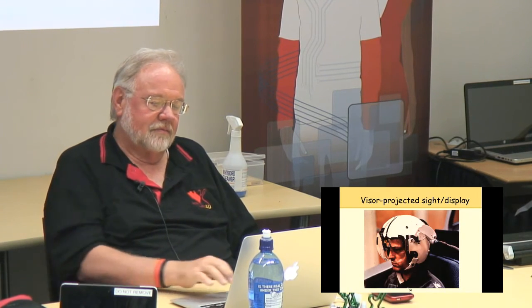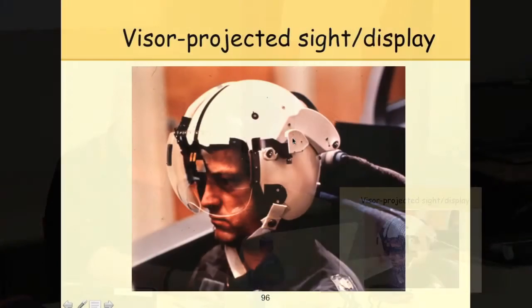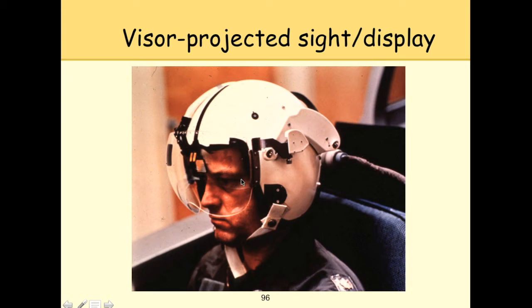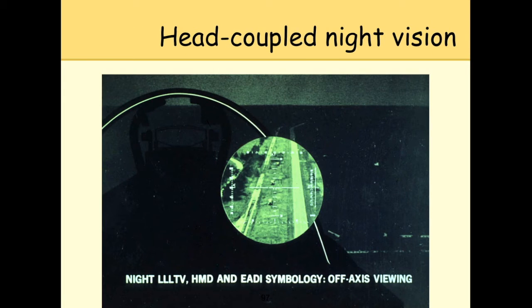Now here it is together. Here's the infrared tracking system, and this is a paraboloid on the visor. We take the cathode ray tube on the back of the helmet, send the image up over the top of the helmet with a coherent fiber optic bundle, bounces into the visor, into a central mirror located at the focal point of the paraboloid, back in the visor in the pilot's eye. So you have this clear see-through display, but when you switch it on, you have this visual display that's out there. Now what happens is that picture you can move around. So now as you're moving your head around, the sensor tracks your head position and you see through the cockpit wherever you look. And oh, by the way, you can put data on top of that.